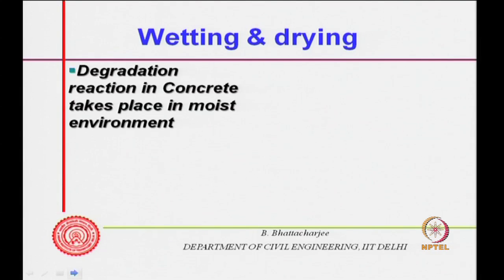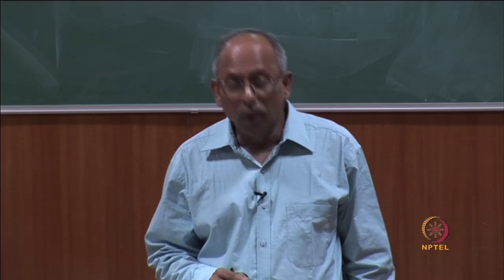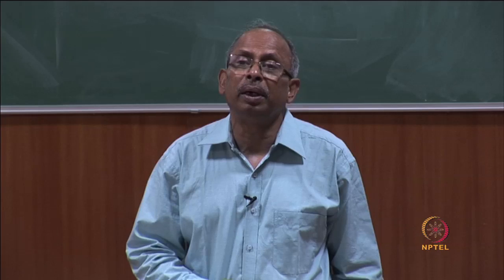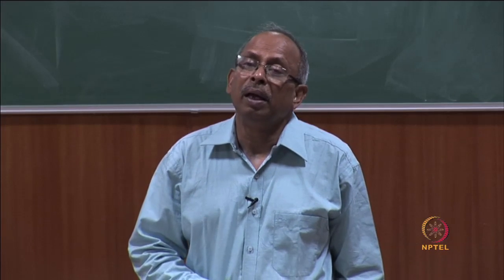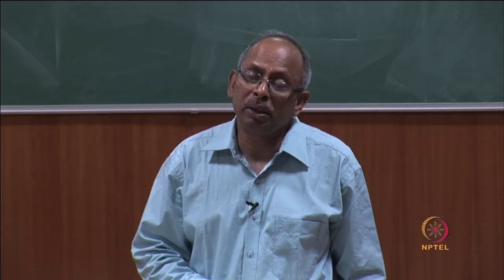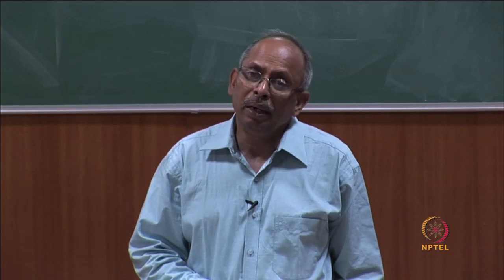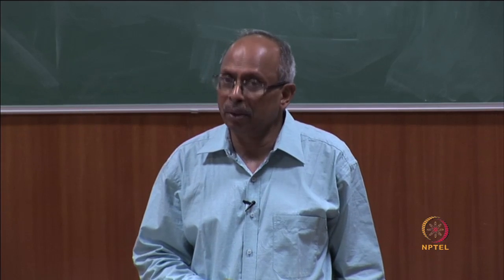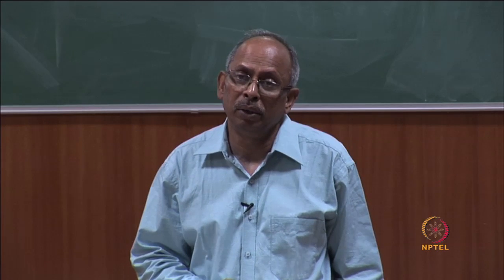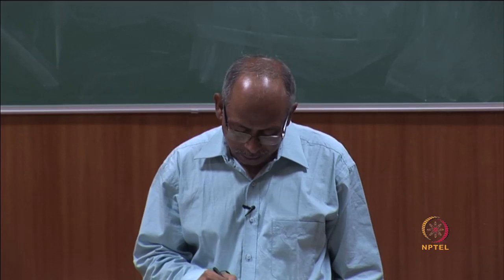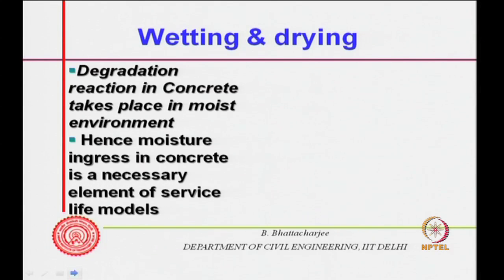Now, we already said the degradation reaction in concrete takes place in a moist environment, and concrete is not under fully saturated condition in tropical climate. Exposed concretes are subjected to wetting and drying. Even in western situations, colder climates, higher latitudes, it is actually under a wetting and drying situation. Hence, moisture ingress of concrete is a necessary element in a service life model.